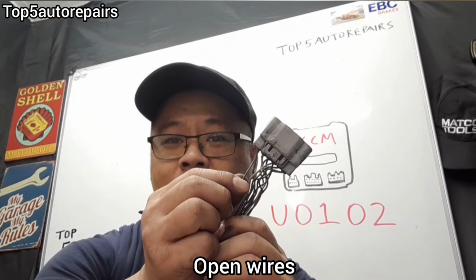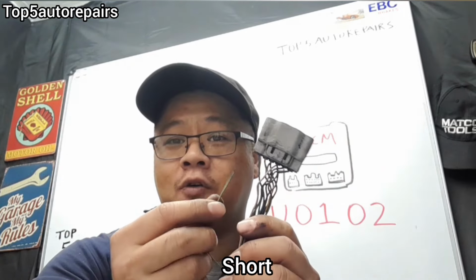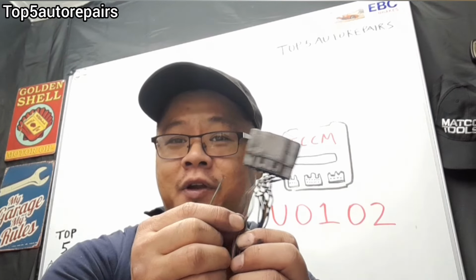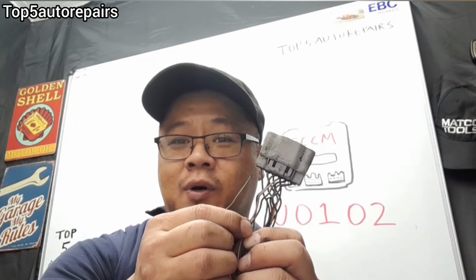So what is an open? This is an open when a wire comes loose or the wire breaks off. And what is a short? Well, basically a short is when a wire comes loose and it touches another wire, or there's two wires that shouldn't be touching, or you can have a short in the transfer case control module, and so on.